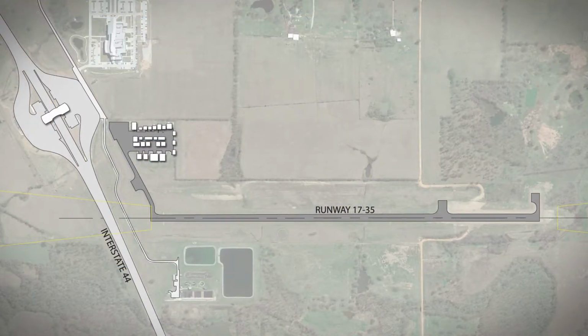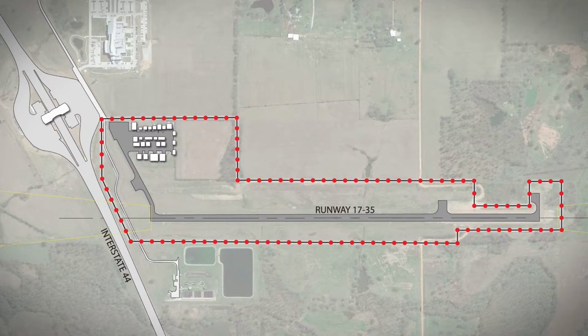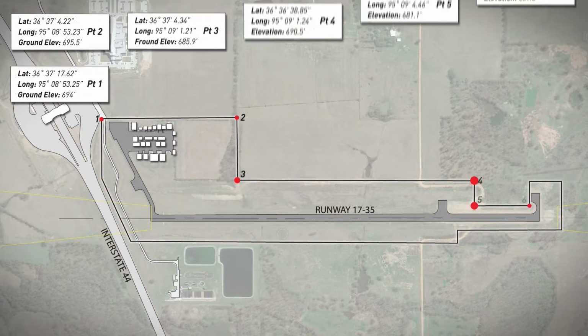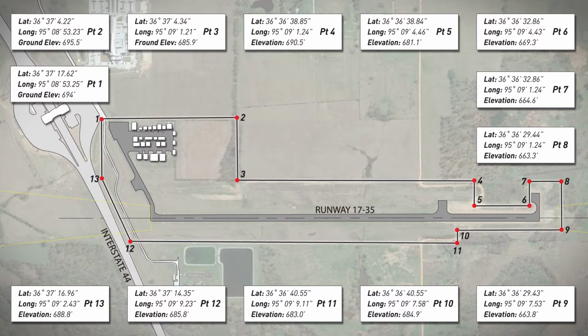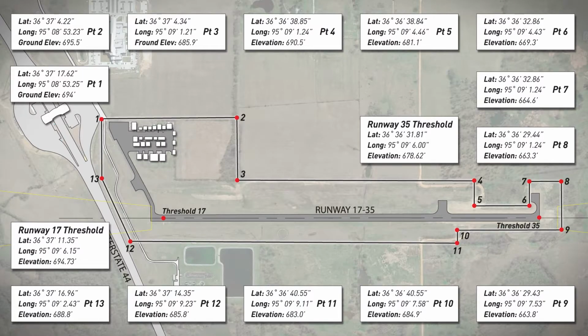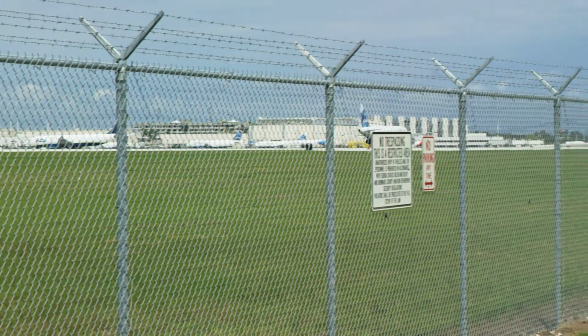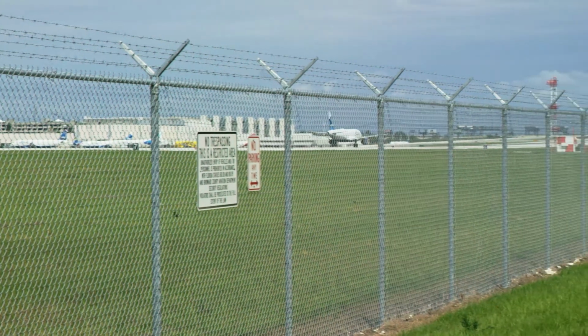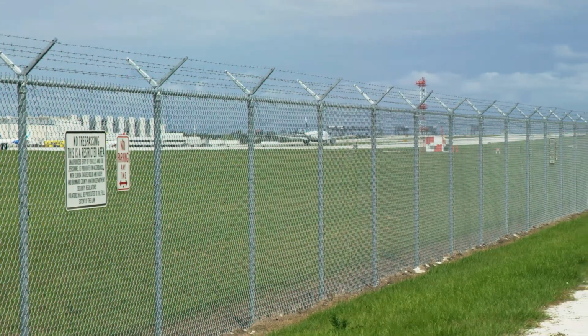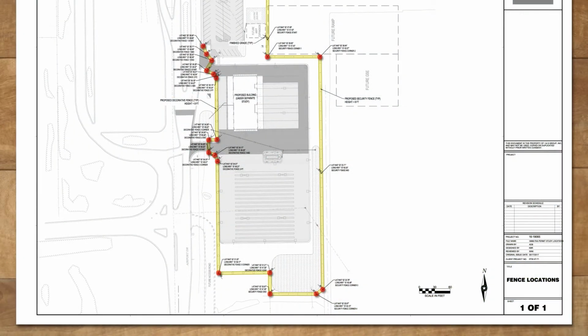Next, when determining points of interest for fences, you do not need to submit every fence post. Points for each fence corner and changes in alignment are typically sufficient. Also consider runway thresholds and runway approach areas for points of interest. In general, a site plan depicts fence location, overall length, transition points, discrete section length, if applicable, AGL, and fabrication material. Metal fencing will require fence detail, site plan, and location where file coordinates are located. The ADO should screen drawings to assess if specific points may be needed by LOBs.